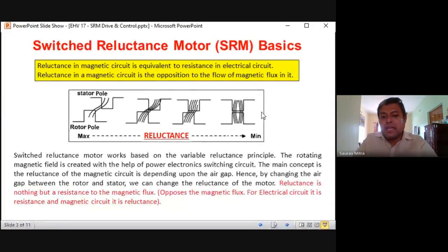This will do two things, and immediately the next pole is made the opposite pole. So this pole and this pole have become the same pole now, and they repel each other, and the next stator pole is made the opposite pole. So repulsion from the previous and attraction from the next will rotate the rotor in the clockwise direction. Likewise it will keep on going.